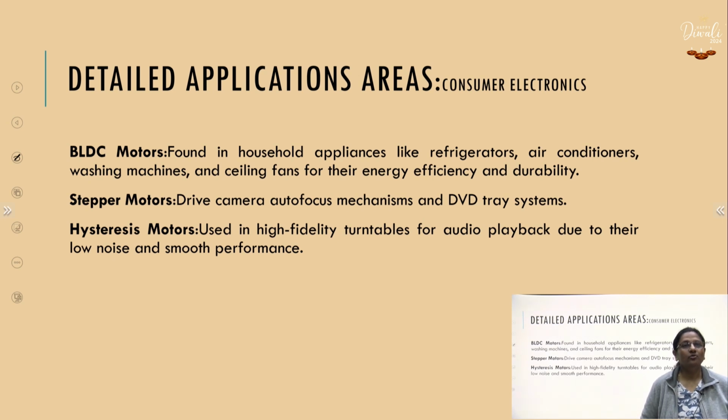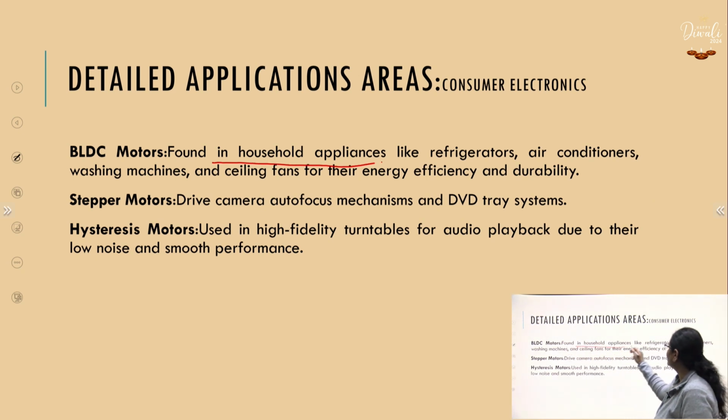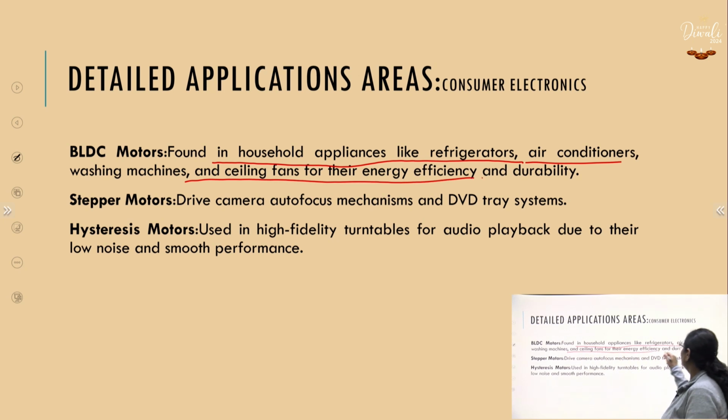The next very wide application area of the special electrical machines is consumer electronics. In consumer electronics, BLDC motors are found in household applications like refrigerators, replacing the traditional single phase induction motor for better efficiency, as well as air conditioners, washing machines and ceiling fans. All these applications were conventionally the applications of single phase induction motors. So, BLDC motor in consumer electronics and household applications.